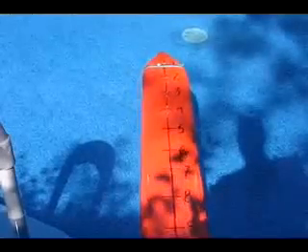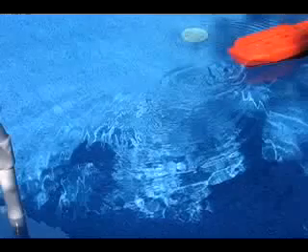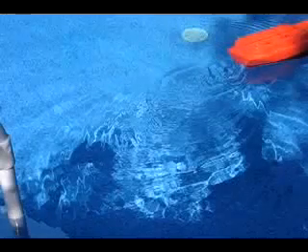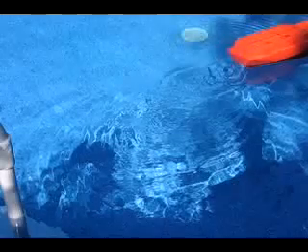Let's try a different type of efficient underwater thruster. Where is the pivot point? It is lying at about 75% of the ship's length, so 1/4 ship's length from aft. From the last three examples, we can see that the classic pivot point theory has its limitations. I will try now to introduce a different approach of the pivot point.